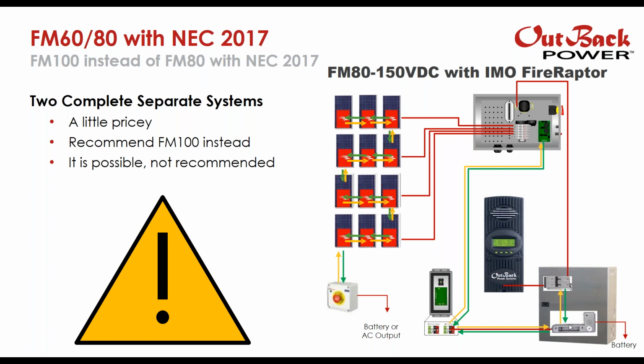So you can't use this. This has been designed for our products and has a specific startup sequence. So if you were to do this, you have to either connect this to the battery and use the DC to DC converter, or to the AC output and use the AC to DC converter.